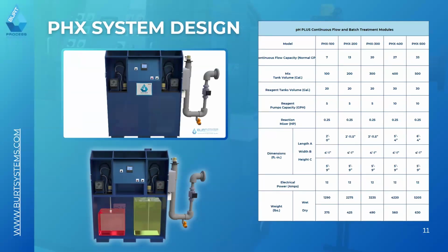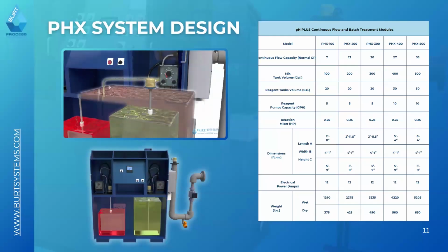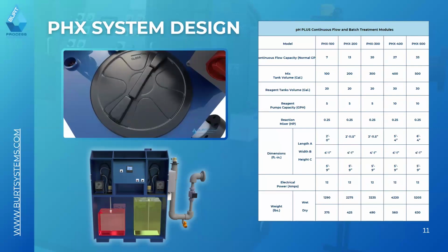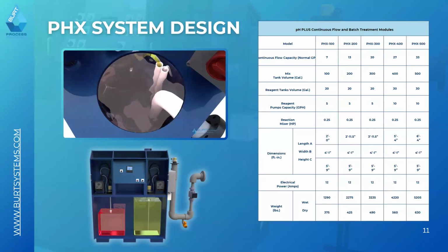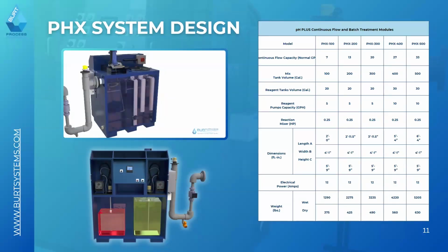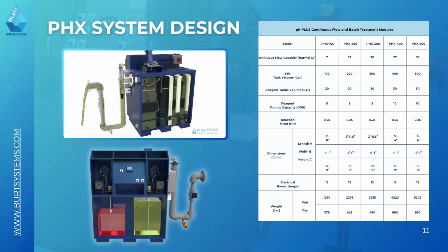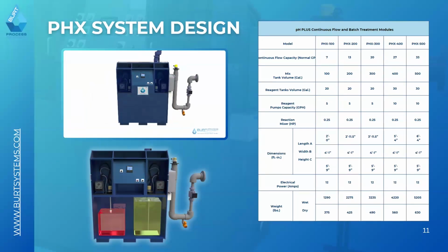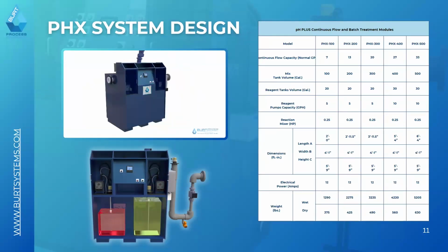One of the things you can do is chemical modeling based on what the waste system is. Typically, you would do a bench scale model. You do actual testing if you were looking at treating waste for metal precipitation or fluoride treatment, where you actually want to do more of a titration based curve, as opposed to a traditional CSTR calculation, which is usually what you would do for most straightforward pH neutralization systems.